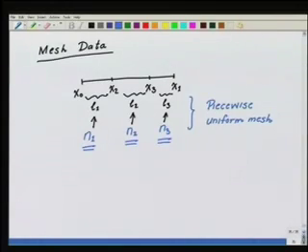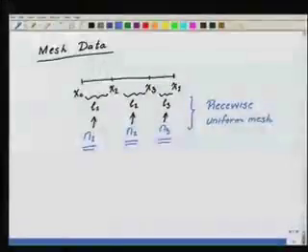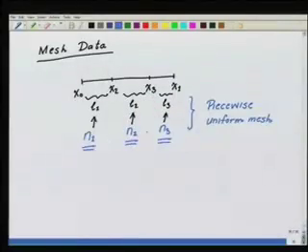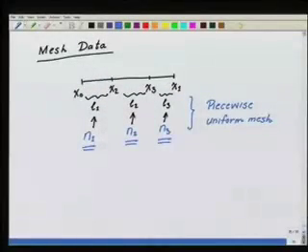Okay? And what we are going to do is make in each piece a uniform subdivision so that I get N1 number of elements in the first piece, N2 number of elements in the second, N3 number of elements in the third. So the total number of elements will be equal to N1 plus N2 plus N3 if all these partitions are distinct. Okay. Now in case one or two of these lengths becomes 0, then this partition, even though we specify it, is going to be trivial information. We really will not use that information.